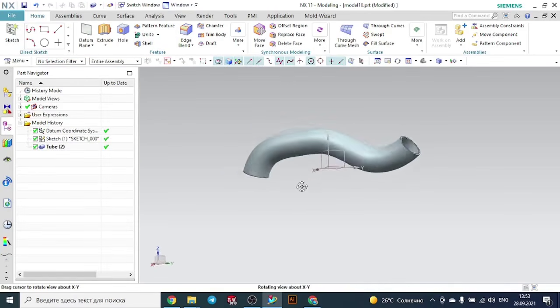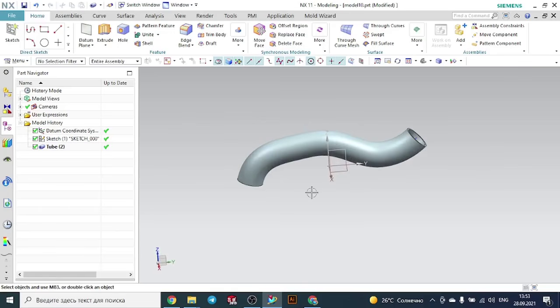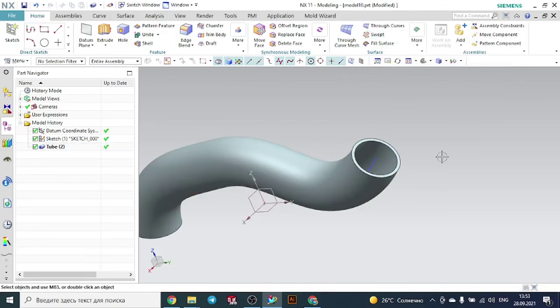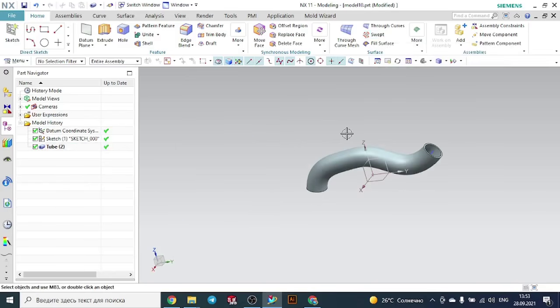You see the tube is created with such a system. So it is easy to create the tube with this one instead of the slab, because it directly creates the inner diameter simultaneously. So it is one more option for how to create a tube. In general, it depends. You just need to draw the cross section, I mean the guide curve, I mean the path, in this case.